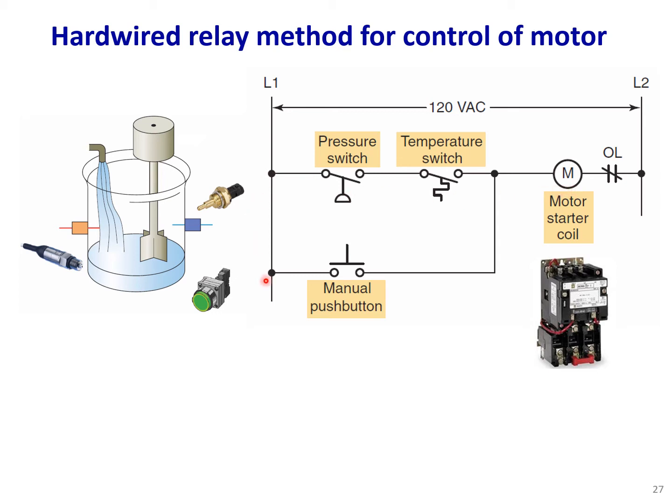Or in the manual mode, if you press the manual push button, then the motor should start. Okay, so we have two branches. These two branches are in parallel. Either this branch, this logic should hold true, or this one should hold true, then the motor will start.